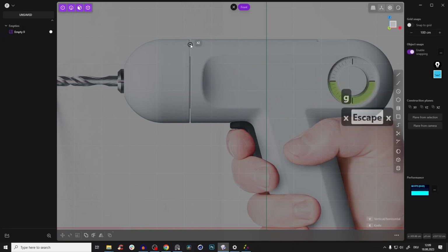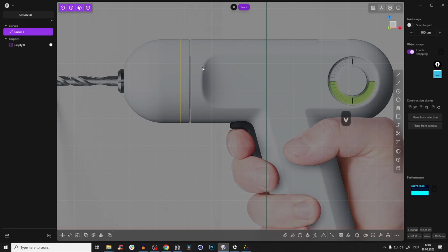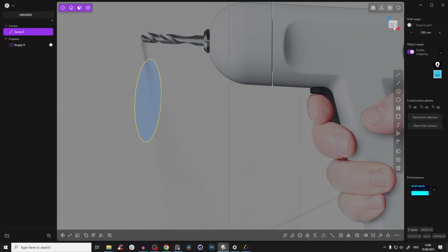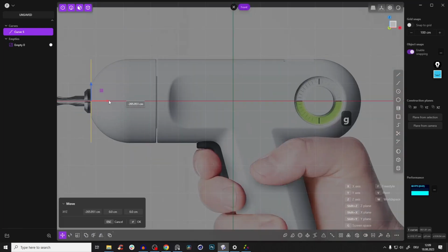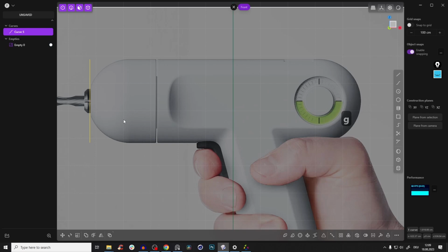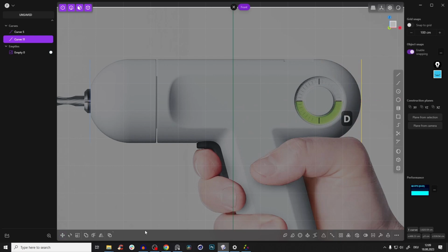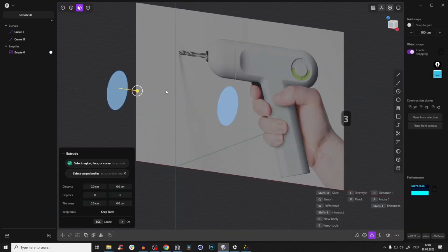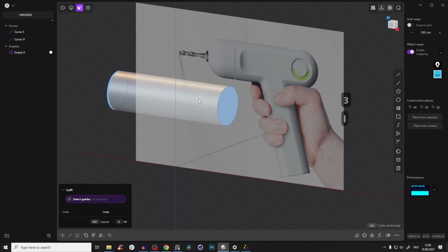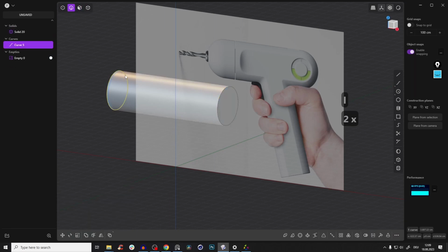So again, create a 2-point circle from one end to the other, and before you snap it, press V here, vertical, horizontal, because then it will just go to the other side. So it will just flip, right? So it will have like this one. So press G and bring that back here. Press OK, Shift D, and also bring this back to this endpoint. And now very simple, select this face and this face with face mode, press L so we can loft it, and we have our cool first cylinder.